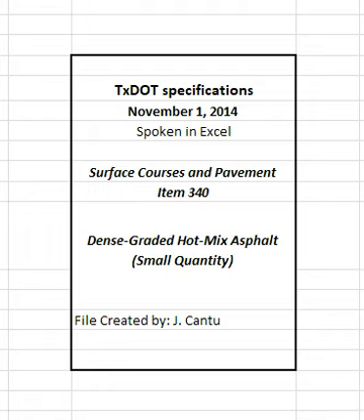2.2 Mineral filler. Mineral filler consists of finely divided mineral matter such as agricultural lime, crusher fines, hydrated lime, or fly ash. Mineral filler is allowed unless otherwise shown on the plans. Use no more than 2% hydrated lime or fly ash unless otherwise shown on the plans. Use no more than 1% hydrated lime if a substitute binder is used unless otherwise shown on the plans or allowed. Test all mineral fillers except hydrated lime and fly ash in accordance with TEX 107E to ensure specification compliance.